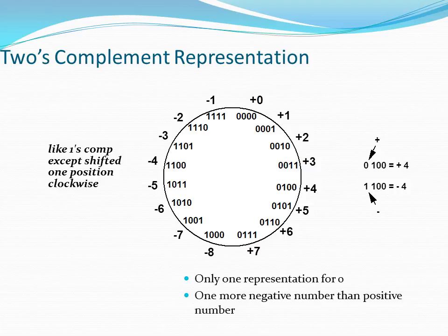So why we use only signed 2's complement representation? Whenever we use signed 1's complement for addition operation, whenever a carry is generated in our addition operation, that carry is again added to our result. So we require additional circuitry. But whenever we use signed 2's complement and perform the addition operation, if there is any carry, that carry is discarded. So this is an efficient process to perform addition and subtraction. So we use signed 2's complement representation for addition and subtraction.